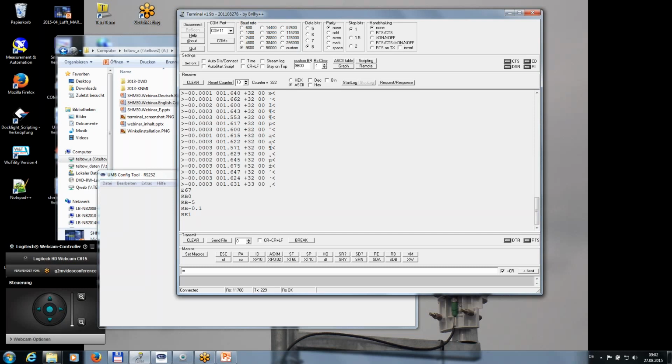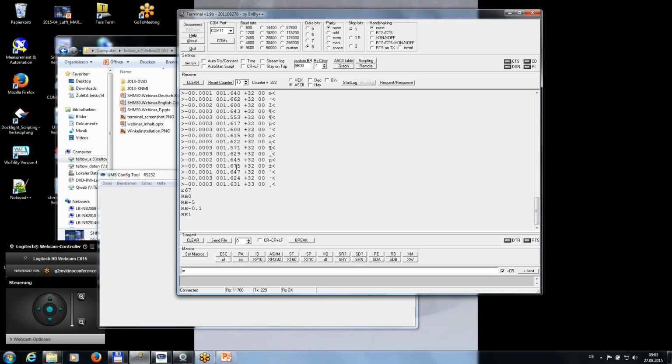And in case any error occurs, like the E61 or whatever, or also other errors like error 15, if you have too much background light or something like this, or not enough signal, then in this case the sensor gives you 3 milliamps or 21 milliamps, and this is part of the UMB config tool also to do an interpretation as undershoot or overshoot, and to interpret these values as errors. It's an FC80 or FC81 error in case of the UMB config tool.